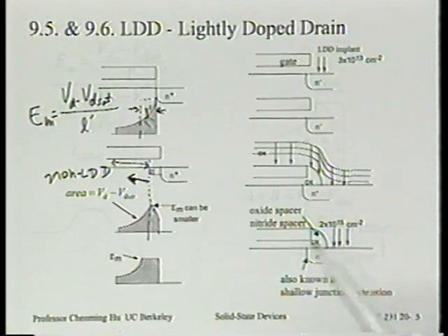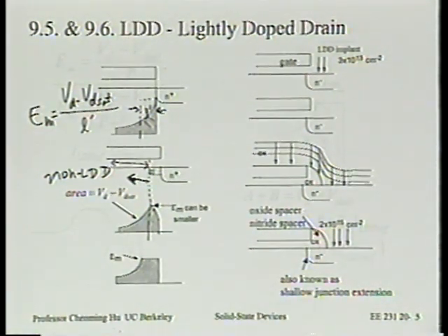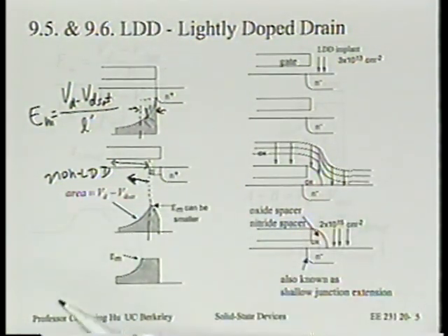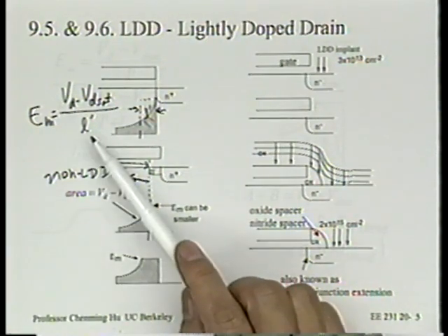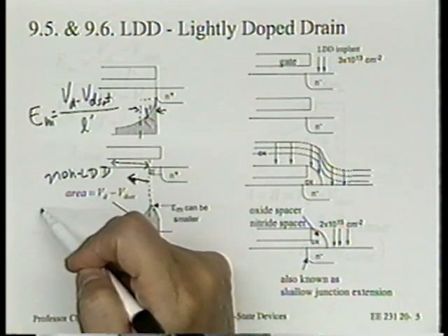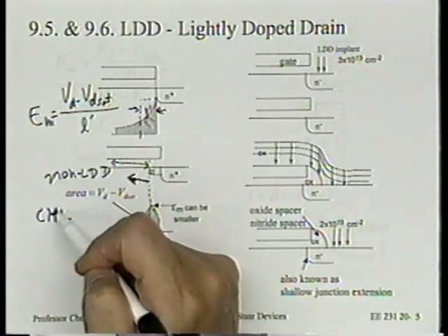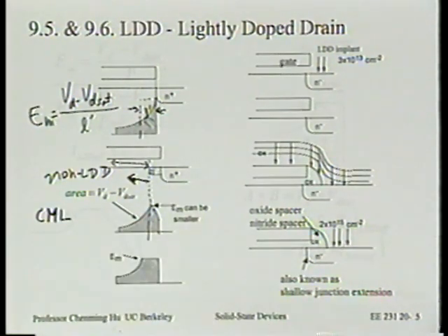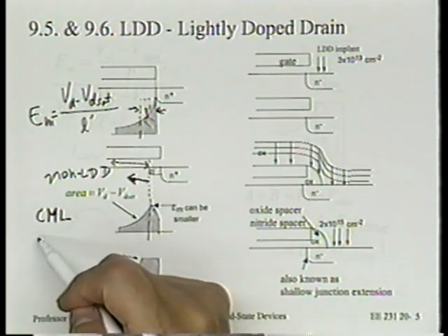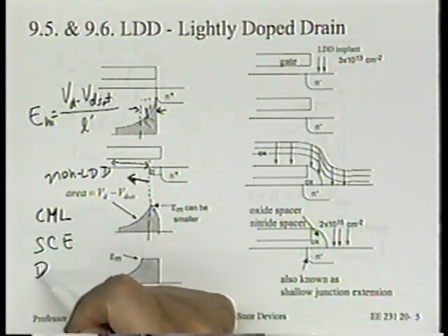Okay, so what you end up doing is, by doing this, you end up lowering the EM, and to the first order at least, not hurting two things, let me point down. Although we kind of use the channel length modulation as the sort of the other conflicting constraint. Actually, a better, more important conflicting constraint really is the short channel effect. All right, short channel effect, or dipole.